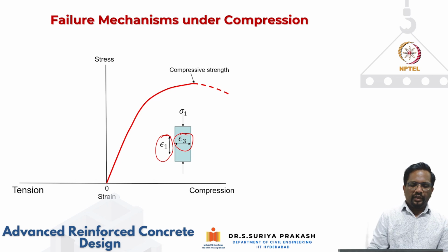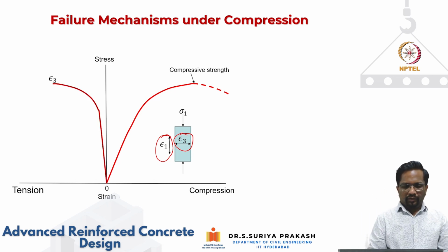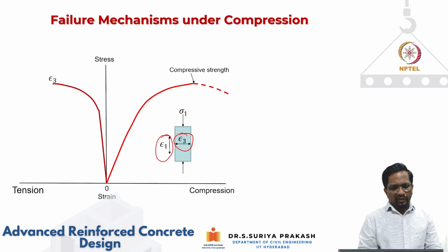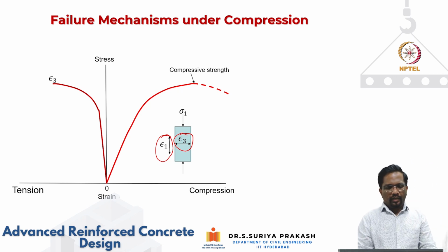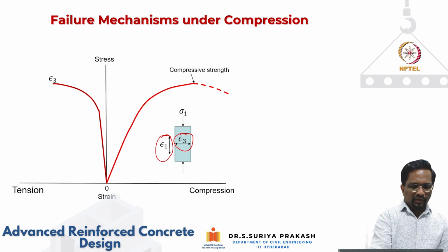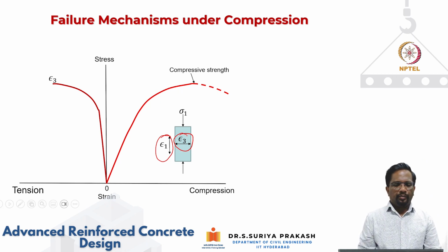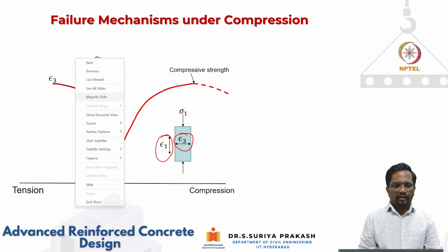So this is the way it is going, because this is undergoing compression, right? So it is there. Now when you plot the same thing, stress versus your lateral strain, you know that there is a Poisson's effect. When I squeeze the material in compression, in the lateral direction it is going to be in tension, right? So that's how this is going to be, and it is going to keep increasing, and then it will become non-linear at a certain point of time. So that is what we are seeing here.